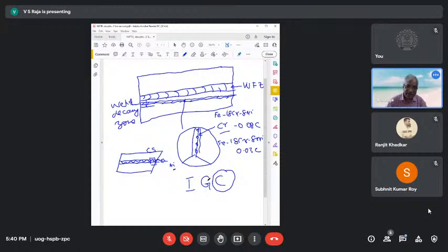Now, the question is, can a metal fail intergranularly? Can intergranular cracking take place? Yeah, metal can undergo intergranular cracking. That can happen in temper embrittlement, for example. Sometimes, if the metal is wrongly heat treated, right, there is some segregation of elements that go to the grain boundaries, and so it weakens the grain boundary. And as it weakens the grain boundary, the metal becomes weaker. So when I apply a load, the crack preferentially travels through the grain boundaries intergranularly.